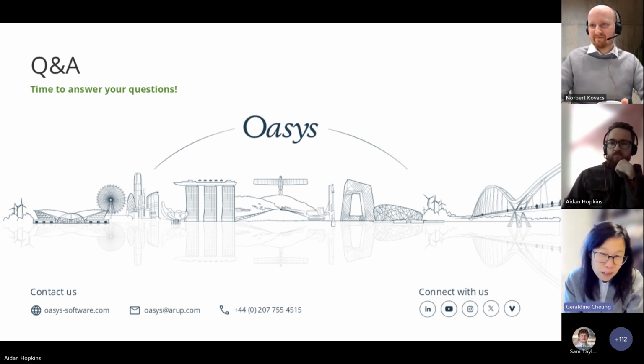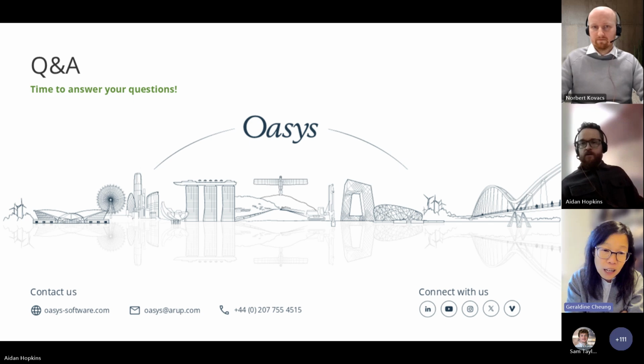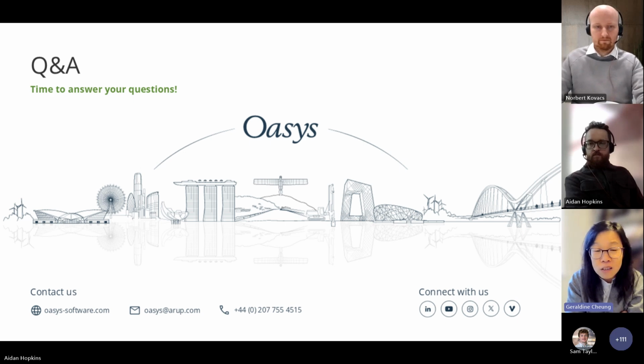We've got the tunnel construction as one of the key things, and as we probably know, the calculation would calculate anything above the tunnel axis level. Therefore, if your utility is located in that zone, even at varying depths along your utility alignment, it will be captured, because one of the other key things we need to put in for utility assessment in the XDisp model is the location and also the level of the utility you want the ground movement to be calculated.